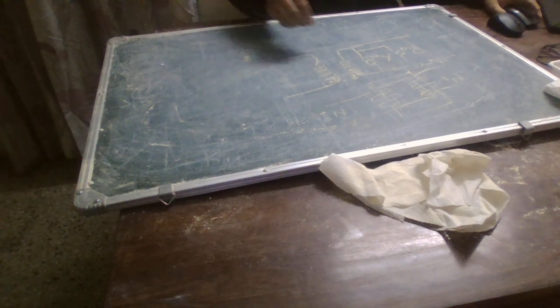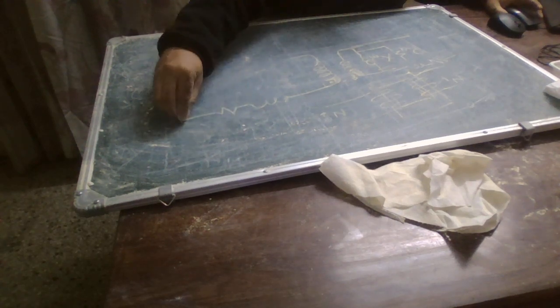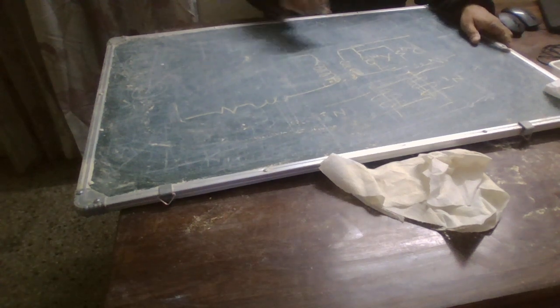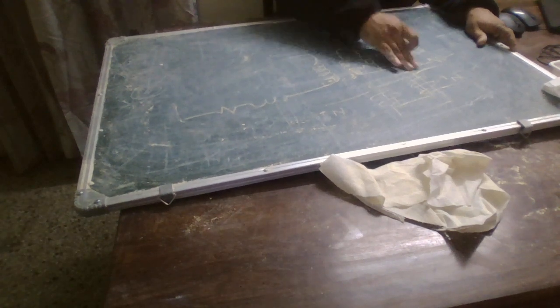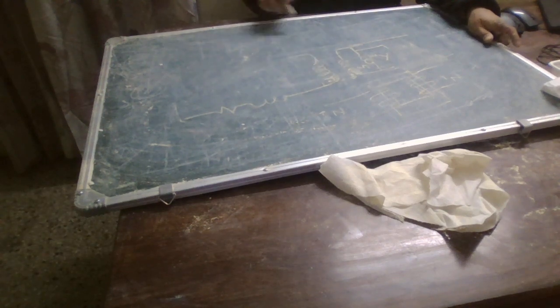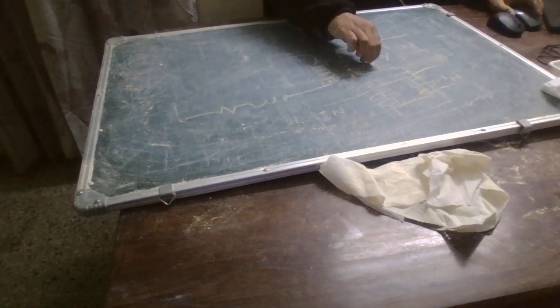Okay, a similar one would be on the secondary side. We can have it here. Now, for power electronics, we are only basically considering this LM. We are not taking the core loss here. For simplicity, we are not taking the winding resistance, and we are not taking the leakage flux into account. We are only taking one thing, which is the magnetizing inductance, and this value is very important for the design of the flyback converter.